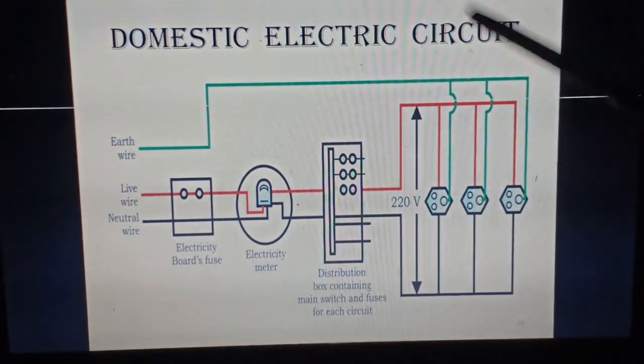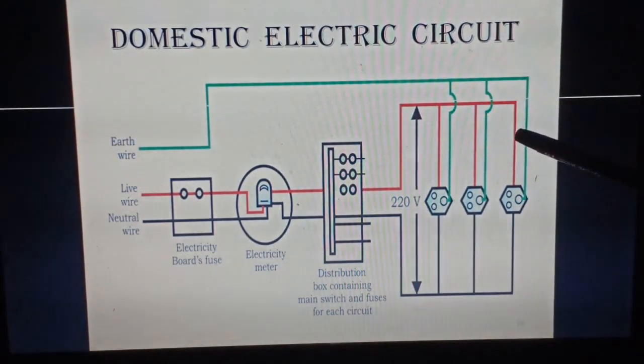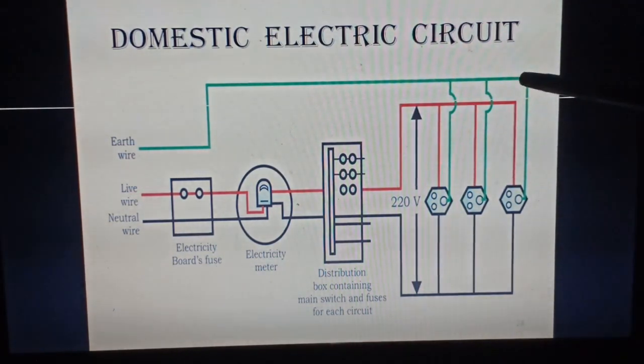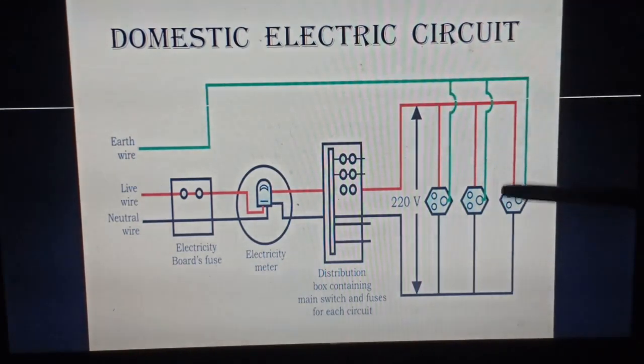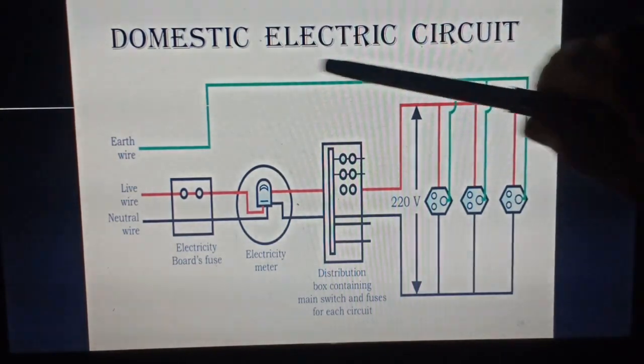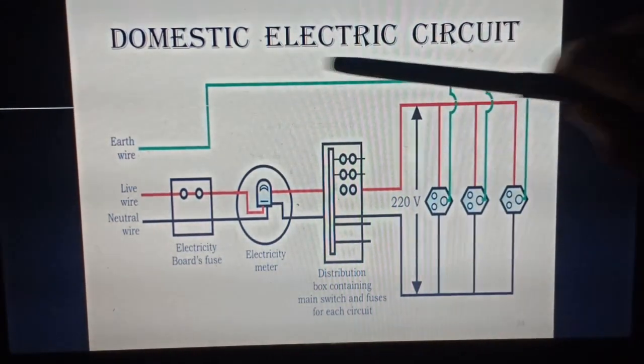This green insulated one, that I was talking about, is very important mainly for those appliances which have a metal body, because sometimes there is a leakage inside the metal construction of an appliance, so there is a possibility of getting an electric shock. The basic mechanism of grounding is that it balances the flow of current through it. So if there is any misconnection or any chance of getting a shock through metal appliances, this wire is connected first. This wire minimizes the chance of getting a shock, because through this wire all the current will flow through the earth.